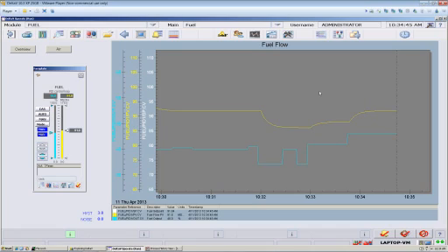The way to distinguish between sloppiness in this example and stickiness is if I were to make another increase in the same direction I had been traveling on a sticky valve after it broke free, it would be stuck again. And I'd go through that same stick, stick, stick, all of a sudden slip behavior. If you find stickiness, that needs to be corrected right away. Sticky valve problems cannot be addressed with tuning.